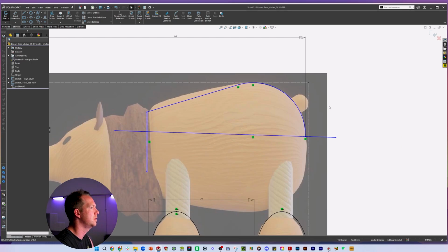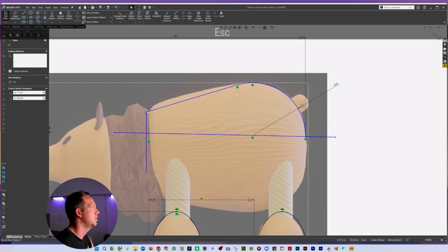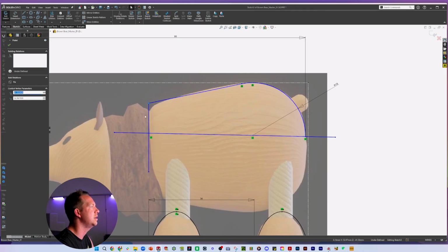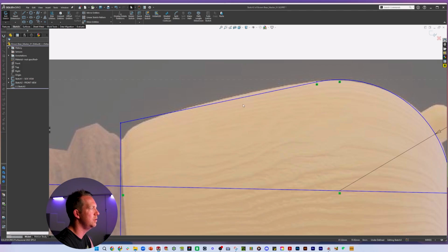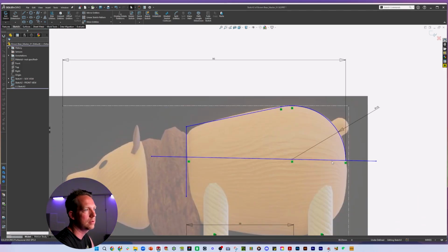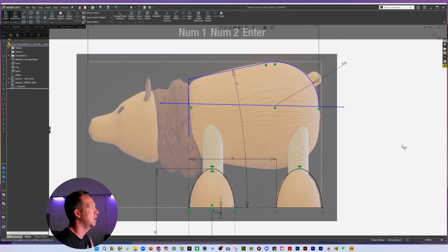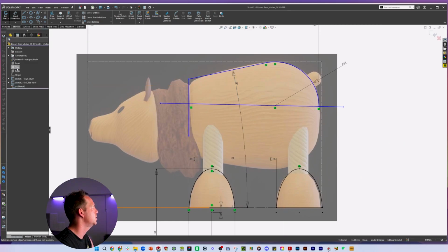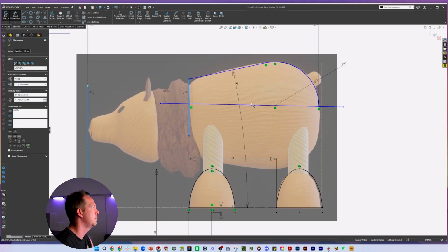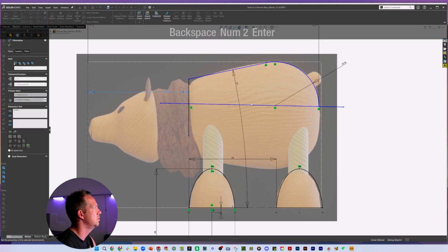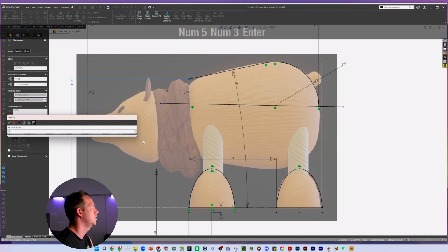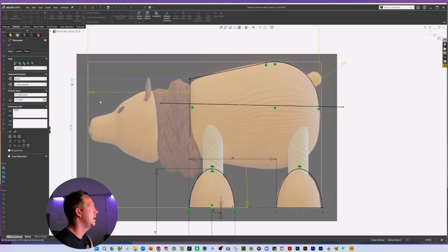All right. So that radius looks okay, so I'm just going to dimension that. Yeah, I'm going to try and drag this line up. And remember, I don't have to perfectly match the sketch. So even though it's a little bit above, a little bit below here, it's going to turn out pretty well. So let's dimension that line with an angle. Okay, an angle of 12. Let's dimension this face from the front, 41, 42. Yep, let's dimension the height, 53. So you can see again, I'm just rounding up those numbers.